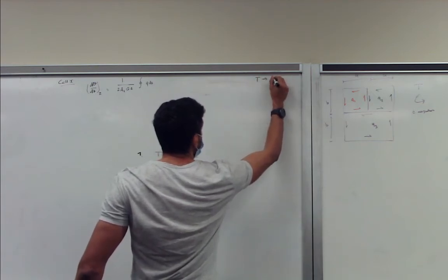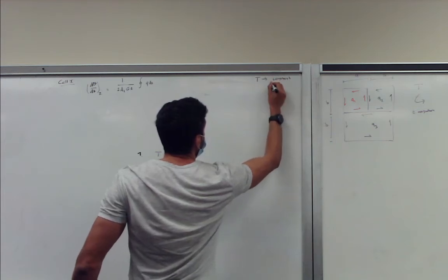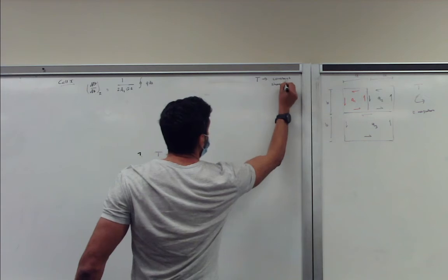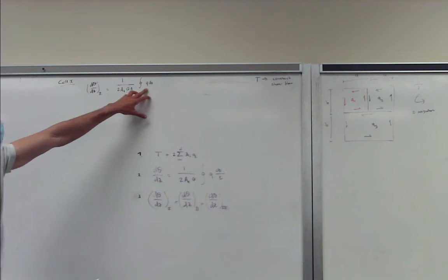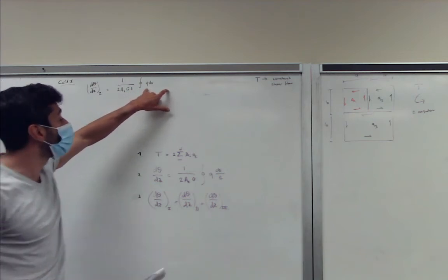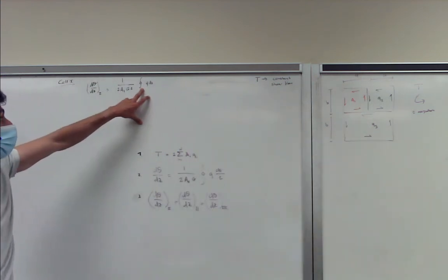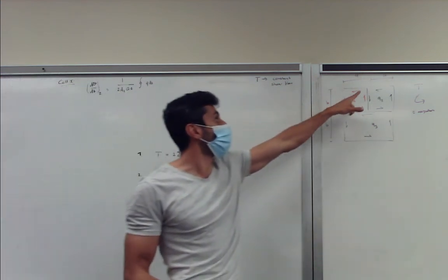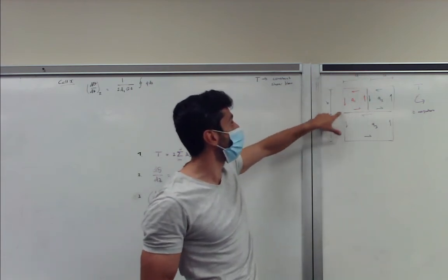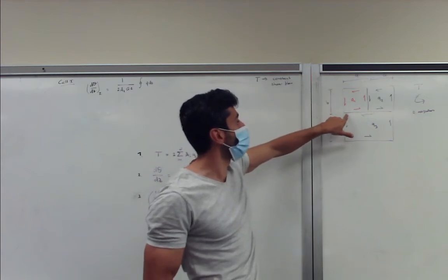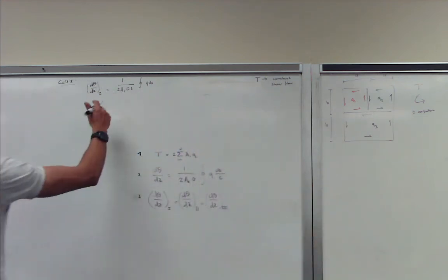We also know from our torsion section that torsion yields a constant shear flow. So q is basically a constant, and we just have to multiply by the corresponding distances, because the integral of ds becomes s. In this case it goes from 0 to a, so that's nothing else than a. From the left, this is 0 to b, so this becomes b. This again 0 to a, so it's another a, and there's another b. So let's write that out.